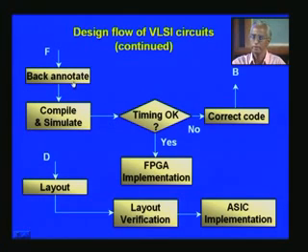And that is the reason, this reflects the actual device, gate primitives that we have already seen before, such as mux etc., LUTs, right? All those will be appearing in this .v extension file, and this will have timing also. So there is another file called SDF, that's a standard delay format. Another group of files are also required, which we will see when we go into the details of that. So only then it can do the back annotation. Back annotation is the one which reflects the actual gate delays.